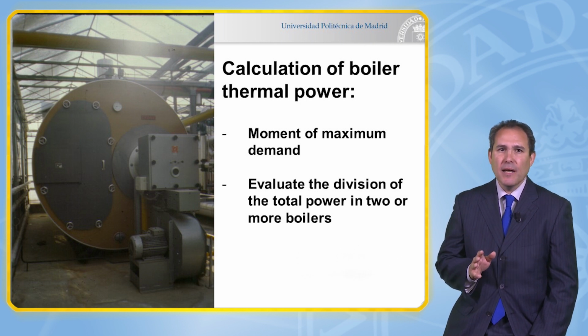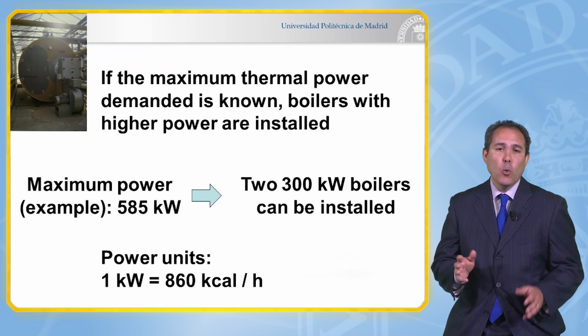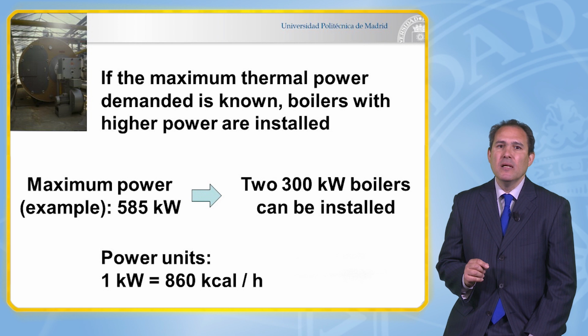In hot water supply, it may be interesting to evaluate the installation of a hot water tank. The tank absorbs the peaks of demand and allows to reduce the necessary power. Without tank, the power of the boiler must be equal to the maximum heat power demanded.